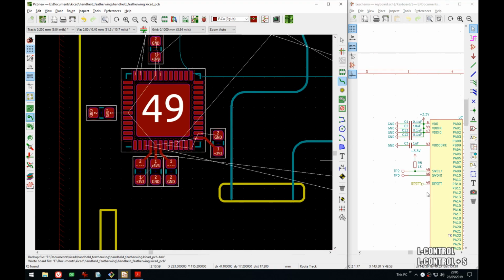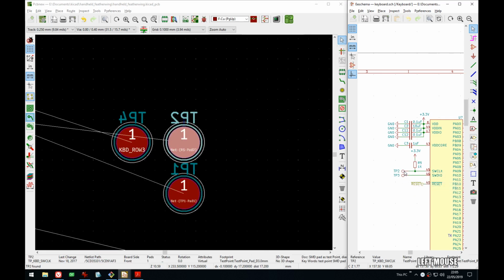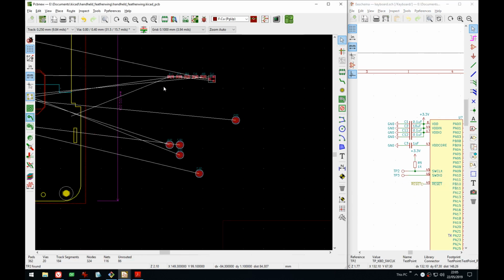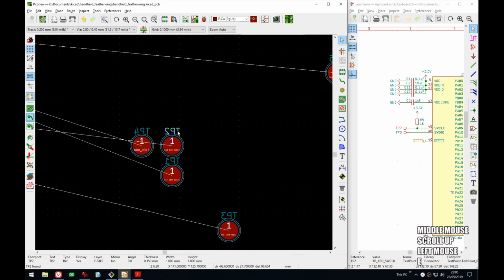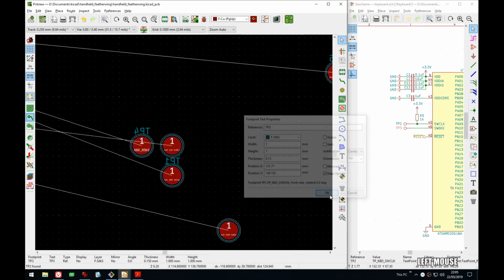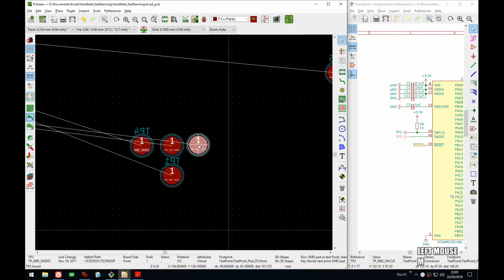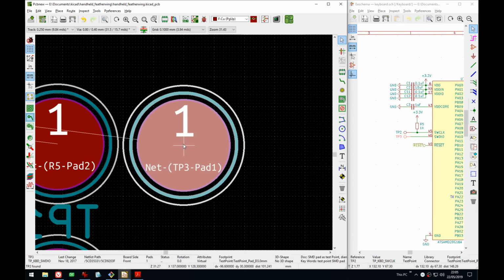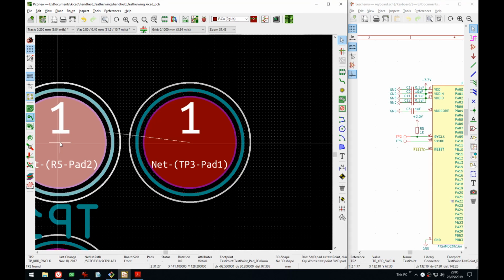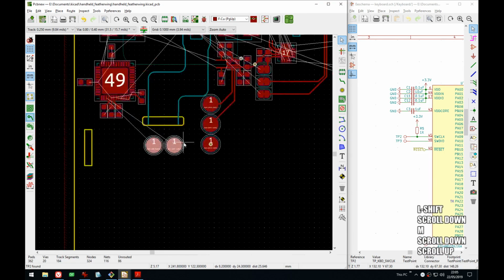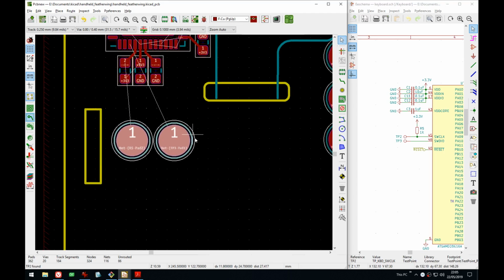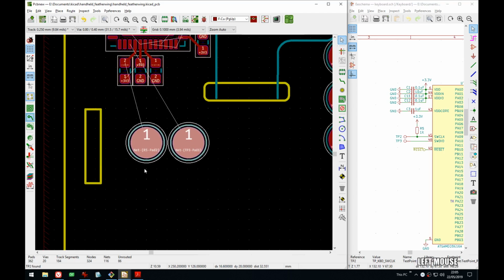Yeah, so we can put the test points. Right, that's the LCD stuff. We'll get to that in a second. So TP2, TP3. There's the one, and there's the other one. I probably want to also put right next to this test points for ground and 3 volts, just so when I'm soldering, if I make a jig, wow, these are huge. If I make a jig, then I can just connect 1, 2, 3, 4, flash it, forget about it.